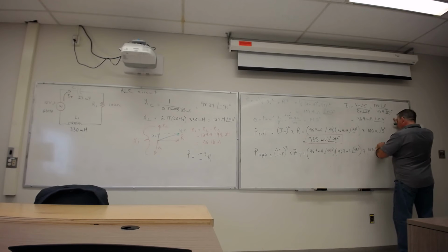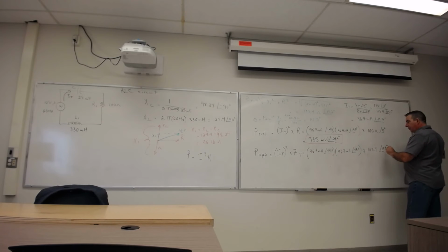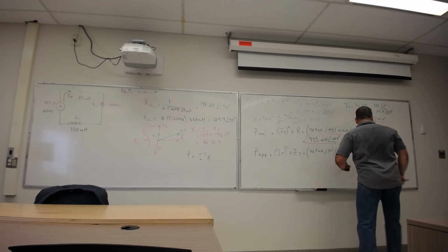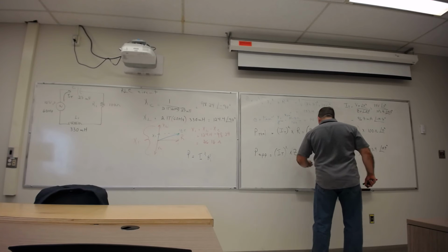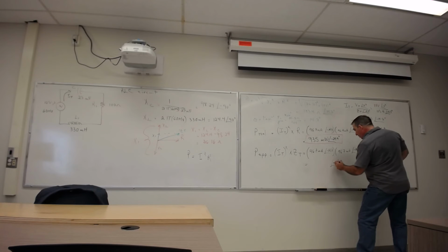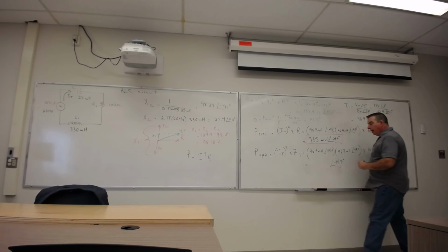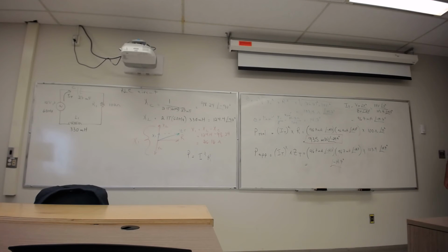103.4 at an angle of 14.7. So I got a negative 14.7, a negative 14.7, and a positive 14.7. So the resulting angle, I know for sure, is going to be negative 14.7, excuse me. One negative cancels out a positive, and you multiply those together. This time you're going to get milli-VAs because it's apparent power.